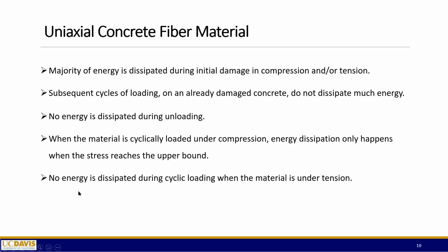And the last one: no energy is dissipated during cyclic loading when the material is under tension. Under compression, subsequent loading can cause further crushing and friction. But when the material is under tension, once it breaks, it shouldn't dissipate any further energy. Once it opens a crack, that crack is there, and only if you close the crack and start pushing more can you plastify. But when you open the crack, that's it for the tension part.